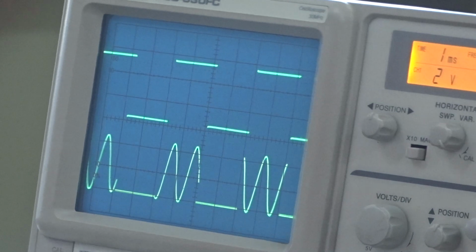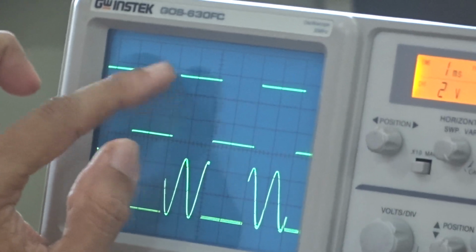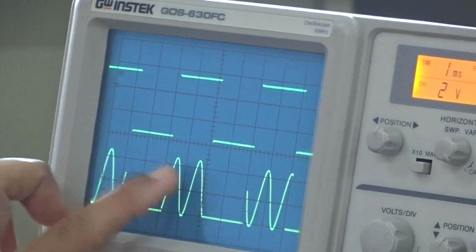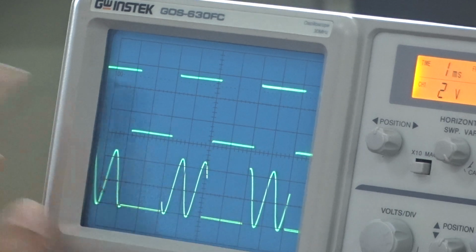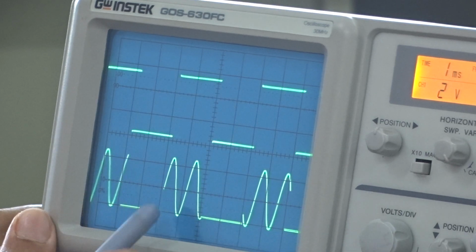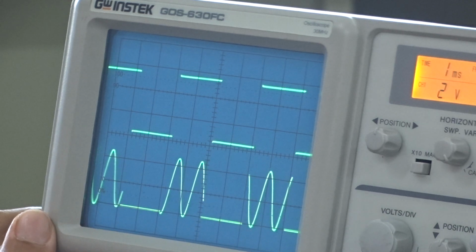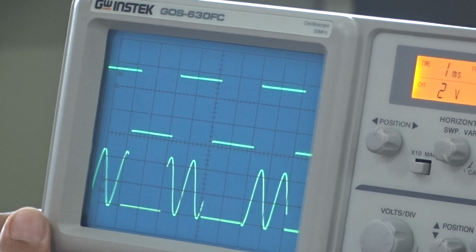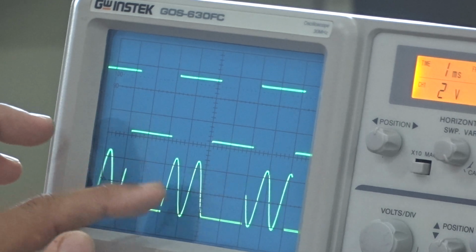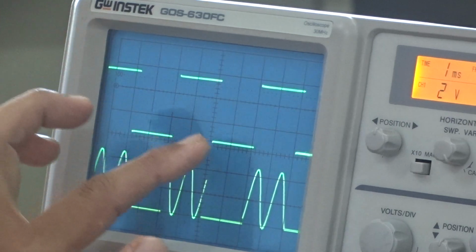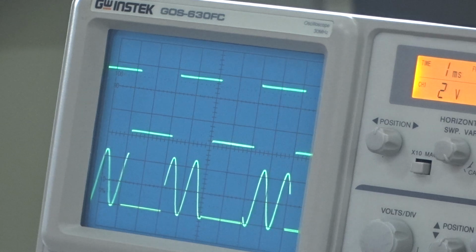So this is the modulator output. As you can see here, for binary 1, that means for logic high, we have a continuous carrier signal, and for 0, the output is 0. That means this output shows the amplitude shift keying output, with logic 1 represented as a continuous carrier transmitted to the output, and logic 0 represented as output 0. So this is the ASK concept, the amplitude shift keying concept.